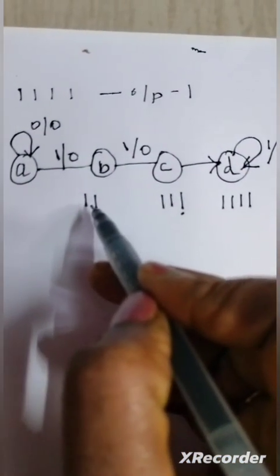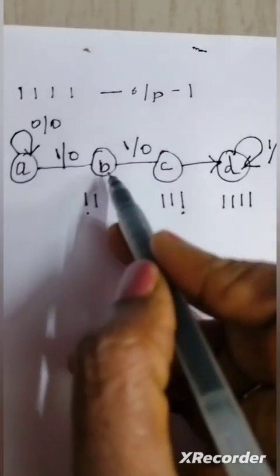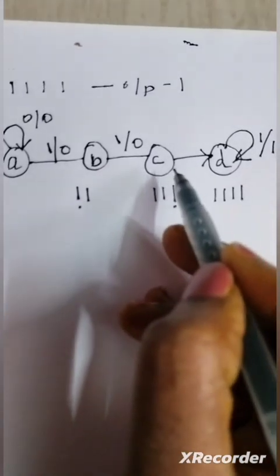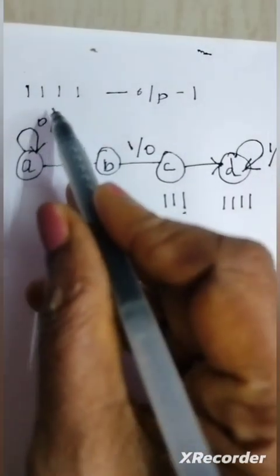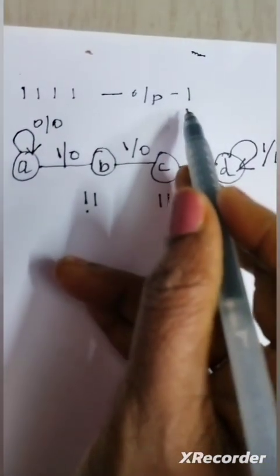Now initially, if you are detecting 1, it is moving to B. When you are detecting 2 ones, it is moving to C. When you are detecting the third one, it is moving to D. When you are detecting the fourth one, it is retained in the same state. So whenever you are detecting 4 consecutive ones, your output is 1. For all the remaining, your output is 0. So that's why you are writing 1 by 1. Your input is 1. You detected the fourth input as 1 and your output is 1.